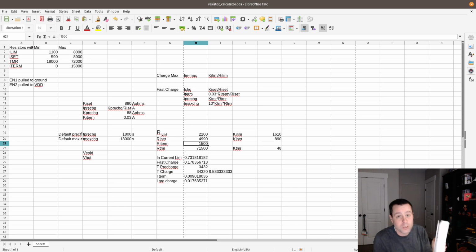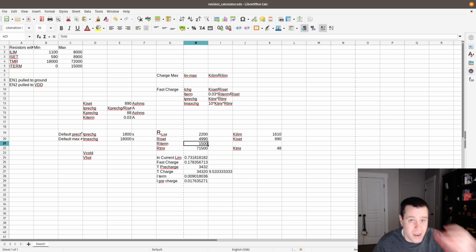When I first was doing PIC microcontrollers, I was super into USB devices and writing code for that, and I really knew all of the details about the power management, but that was almost 10 years ago. I thought that the host limited the current. So when it says 100 milliamps is the limit, I would have expected it to limit me to 100 milliamps when I plug in my device. But it's not.